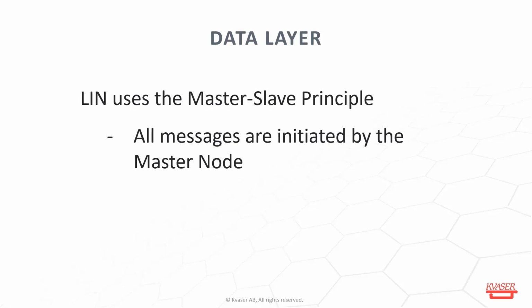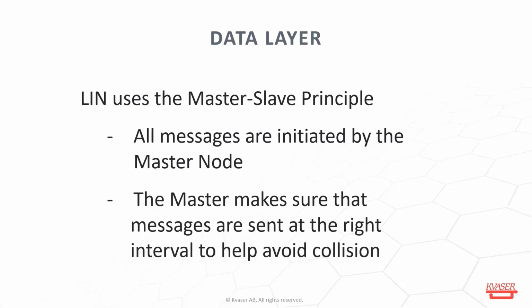All messages are initiated by that master. The master sends data out or asks a node what's going on, and the node replies. The node itself won't put a frame itself out on the bus on its own. The master also controls how messages are sent. That will allow for better control to avoid collision. The master will set the timing. It will tell the nodes the speed of the bus so that the slave nodes themselves will auto-baud to what the master wants.